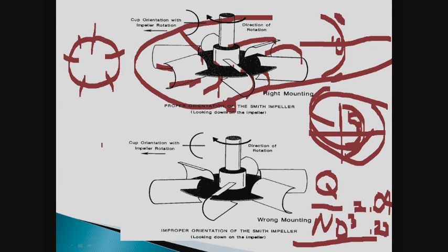So you come along and you put on 12. Okay, and so that's an improvement. It's not going to be a double. 6 going to 12 is a double in blade number, but oftentimes blade effects in mixing is 0.4. So if I went from 6 to 12, the ratio of performance might be blade number to the 0.4 there.